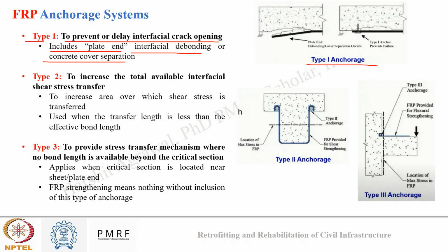And here, by simply using a nut bolt anchorage system, we can improve the bond strength between the FRP and the substrate. Here you saw a hole was drilled in which the FRP was screwed with the substrate, which improved the bond.